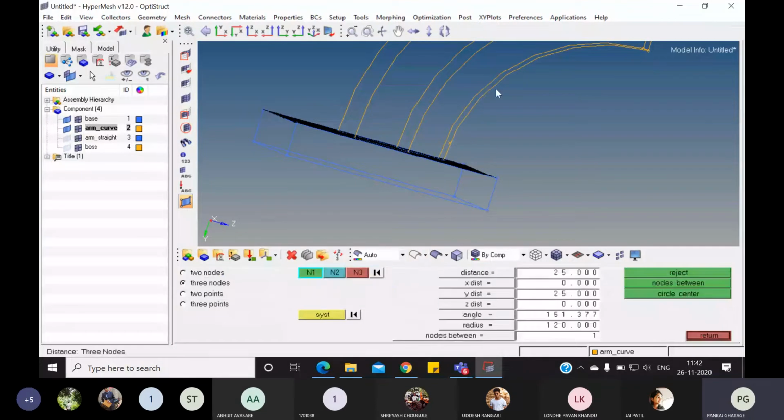Okay, select again this one of the line, so keep pressing on that particular line, so then it will be selected. If you just make a single click over there, that will not select. You have to press that mouse button continuously, then it will be selected. Now on the same line, node 1, node 2, node 3, three nodes need to be highlighted. So first here, second one here on the same line, and third one somewhere here.